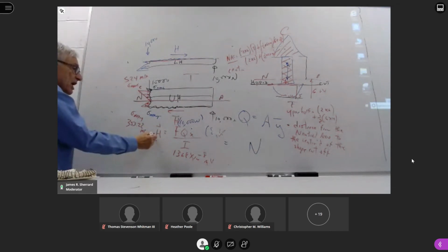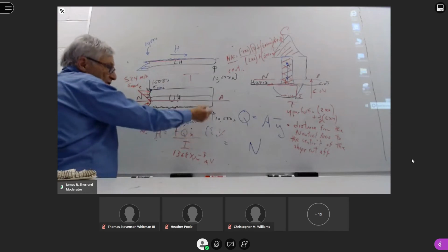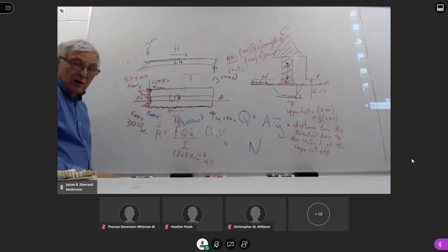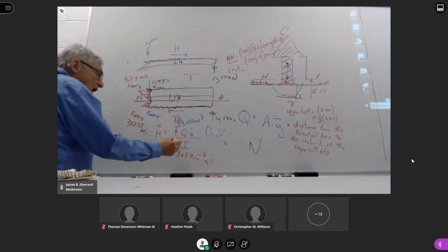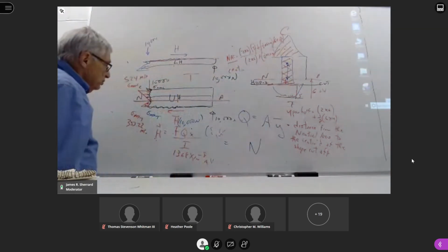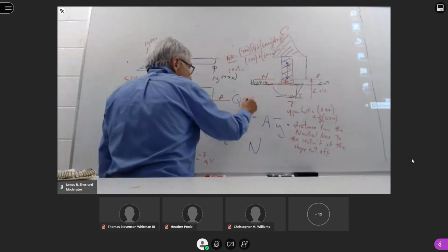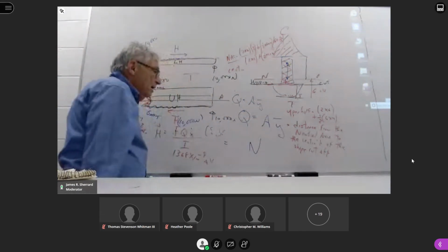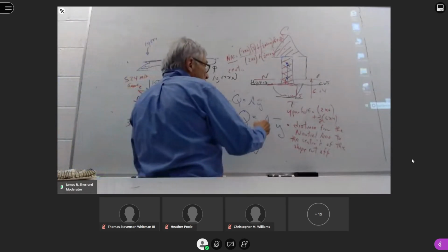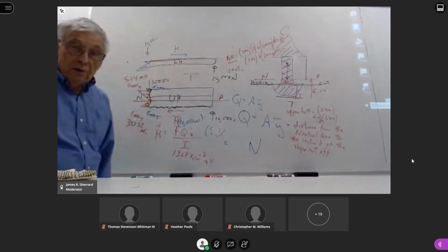When you go to calculate this H from this view, F is still the same, because that's the vertical cut force. X is still the same because it's the length of the cut. I is still the same because it's the rectangular moment of inertia of that entire cross-sectional shape. What is Q? Q is still area times Y bar, but what is the area this time? The area this time is only the area of the semicircle.